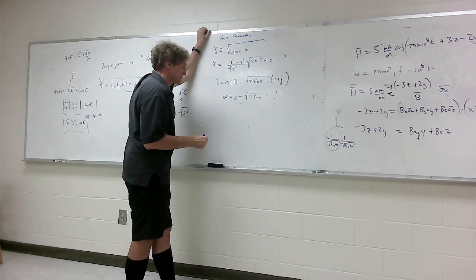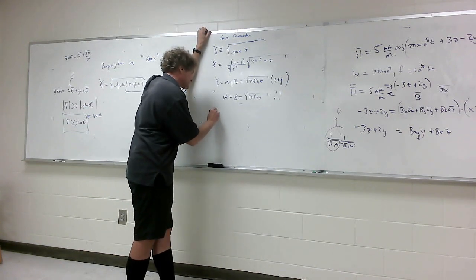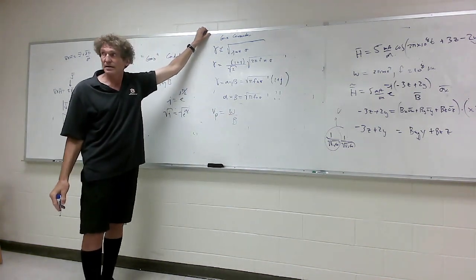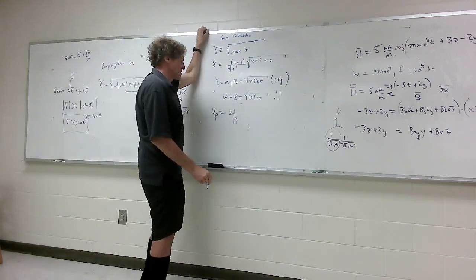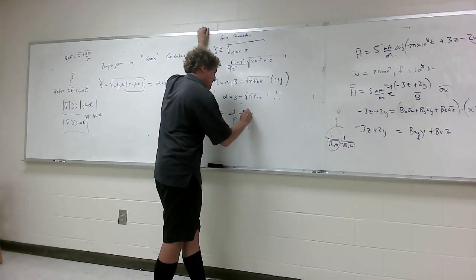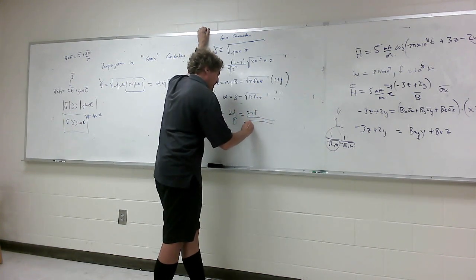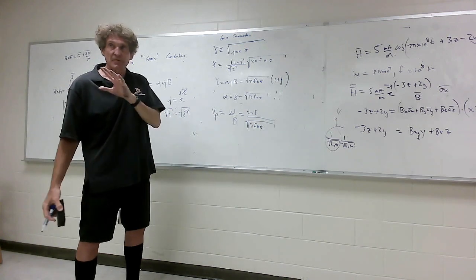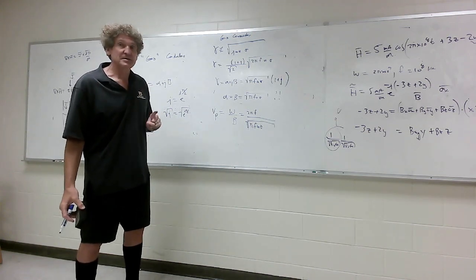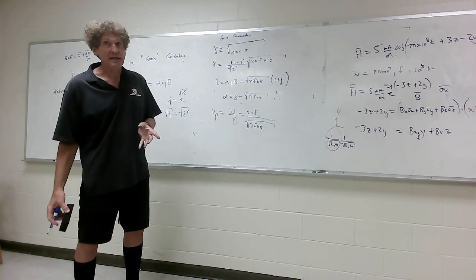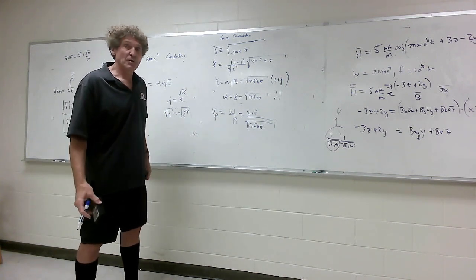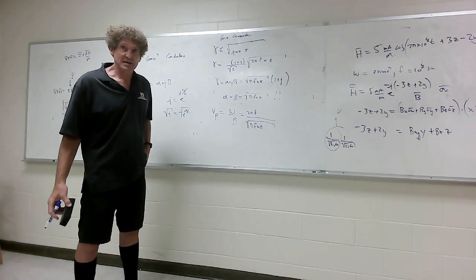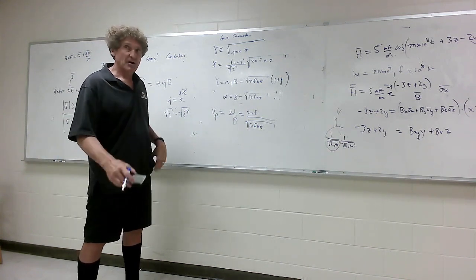Now, another thing that's interesting is what happens to phase velocity? Phase velocity is omega over beta. You agree with that? Take a look at what happens here. Well, omega is 2 pi f, and then over beta is square root of pi f mu sigma. Now, I'm putting it down before I start erasing things. I want to make sure you all follow me on this. The phase velocity is the thing that gets people. This thing's going to be a whole lot less than the speed of light. Matter of fact, at some point you can outrun the phase velocity in good metals at a certain frequency. But we'll talk about what that really means.